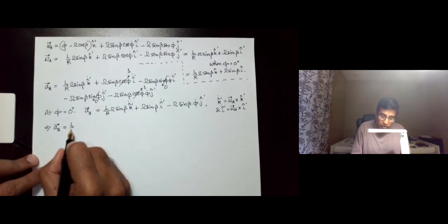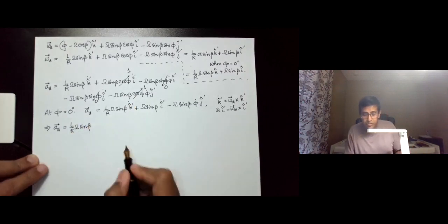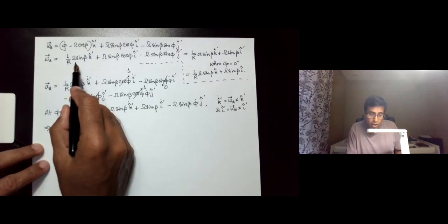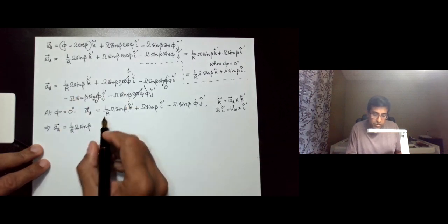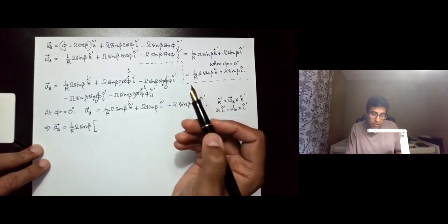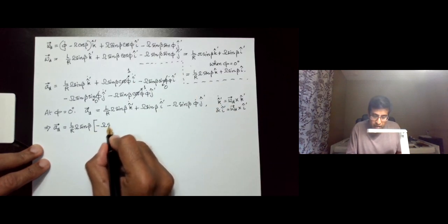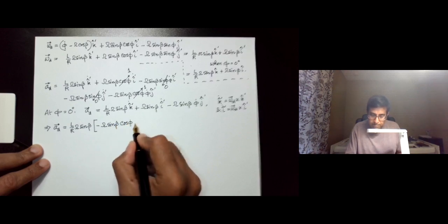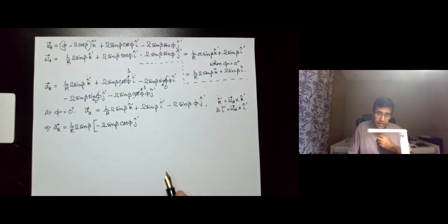So we have L over R, capital omega sine beta, and now let's do k prime dot. So k prime dot is omega d cross k prime. So k prime cross k prime is going to be 0. i prime cross k prime is going to be minus j prime. So we'll have minus capital omega sine beta cosine phi j prime.